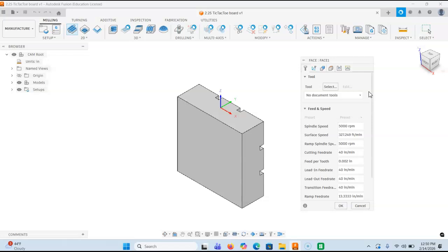It's very essential when we're working with raw or even uneven material to use this to set the stage for accurate cuts and future tool paths. And of course, that also controls depths of cut and other operations as well.